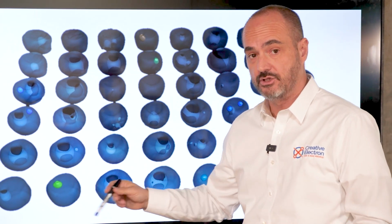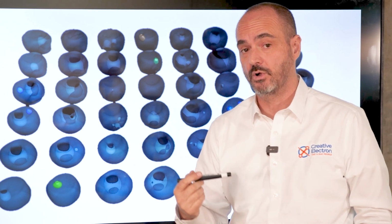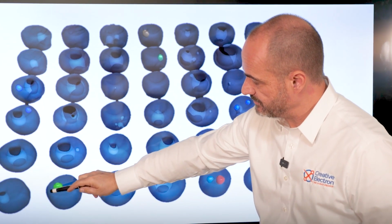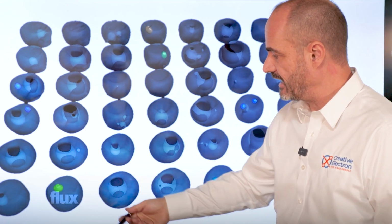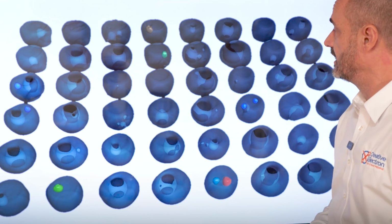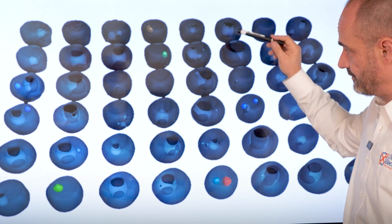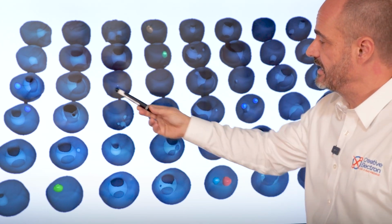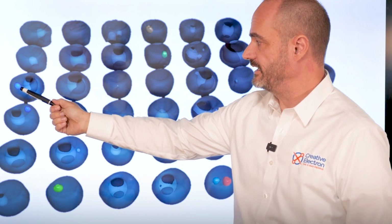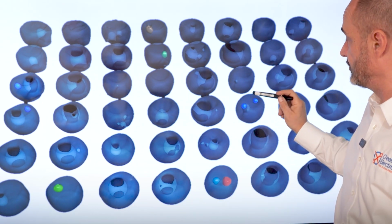Not only can you pass-fail on area, you can pass-fail on volume, which is how much of this BGA is represented by flux or trapped air or whatever else might be inside the BGA that's not solder. The other cool thing about proper 3D is that you have the location of the void on the ball. A void right in the middle of a solder ball is different from a void that's actually connecting to the PCB or to the BGA.